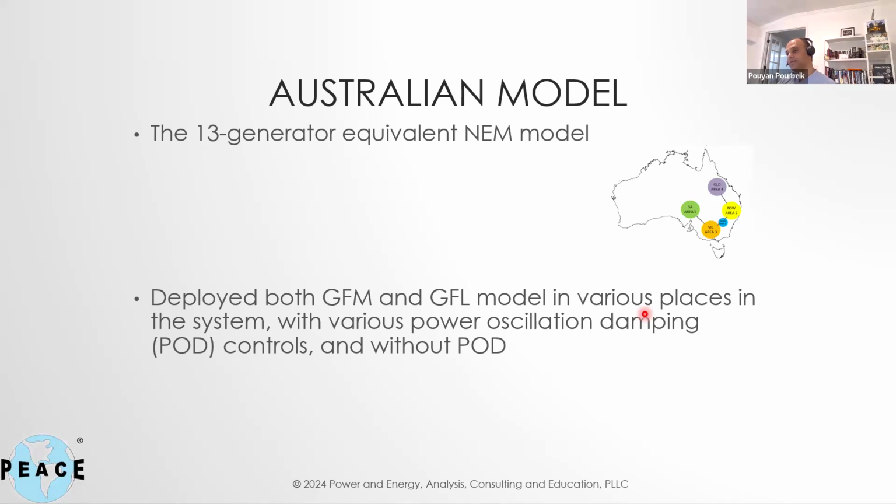By grid forming, we mean the control strategies that focus mainly on voltage and frequency control, so they're not tightly controlling current in the transient time. There's some leeway there to give you great gain margin, whereas grid following inverters are the classic stuff that we see deployed today and have been for decades, a very tightly controlled, current-regulated device.